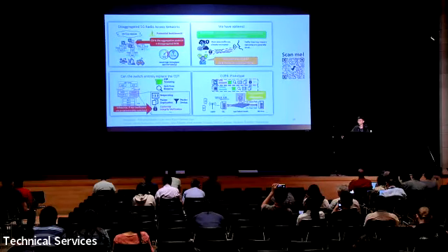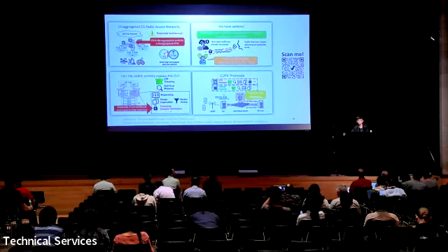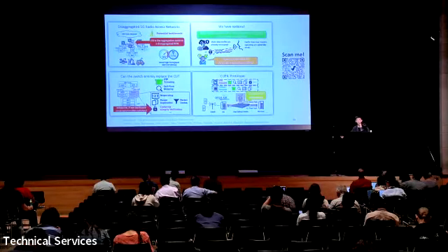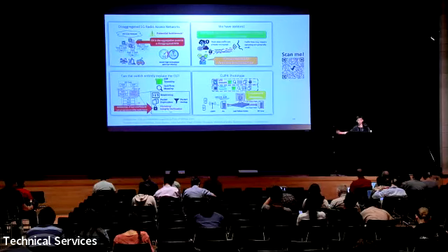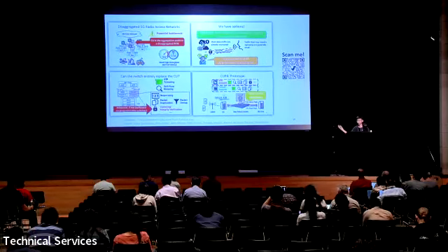Okay, that's a good question. At the moment, in our prototype, we only included basic layer 2, layer 3 functionalities. So in fact, we did not consider what additional functionalities will be needed in the top of rack switch yet. But even so, I believe there are ways to solve it. In a switch, there are multiple pipelines. We can always join pipelines in order to have a longer pipeline to support this functionality.